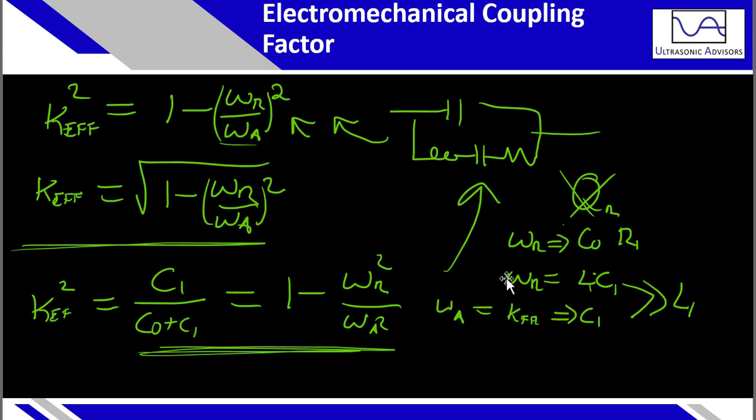It'll be likely to fit the resonance and anti-resonance features better. It's more appetizing to look at it, but it will be more accurate for you to use quality factor because you are using only resonance calculations. The more parameters you can extract in a smaller frequency range, the better it's going to be. Because you could also include off resonance capacitance here and do calculations as well.